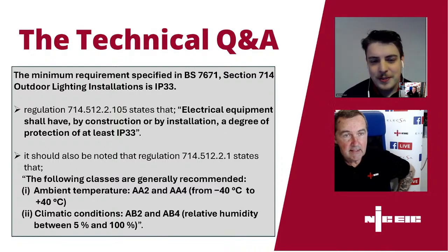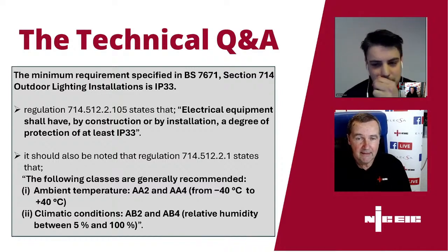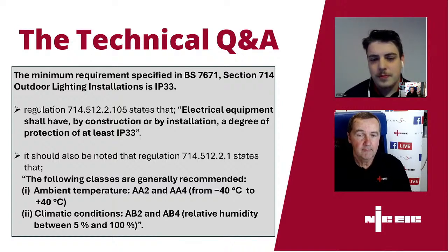Sometimes people get a little bit confused, in that they think, oh, I'm greater than the maximum permitted Zs, therefore my protective device isn't going to operate. It will operate, it just won't operate in the required time to achieve your required disconnection.